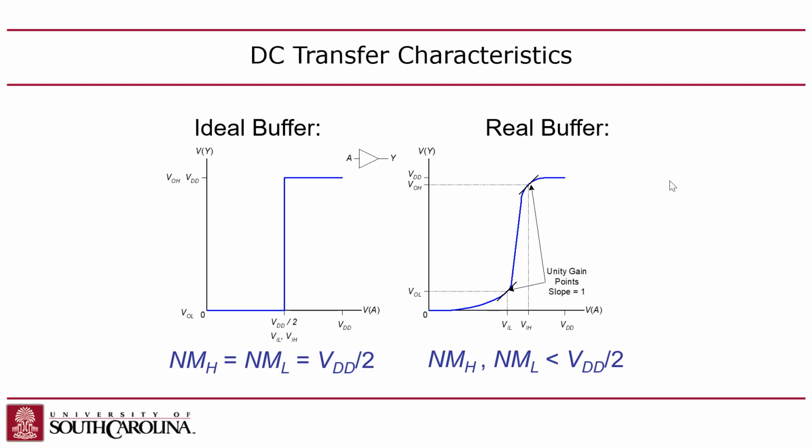If you look at the voltage where that happens, that's really your VIL, right? So as long as your input voltage is below the unity gain point on, in this case, a buffer gate, which is used as the model for this, right? As long as you stay below the unity gain point, which is VIL, fine, right?